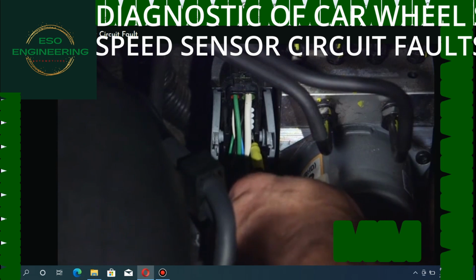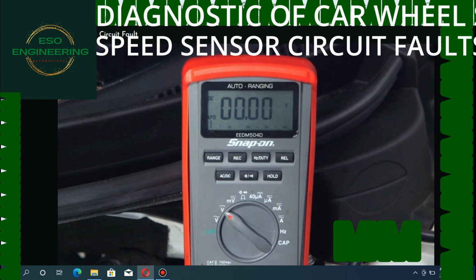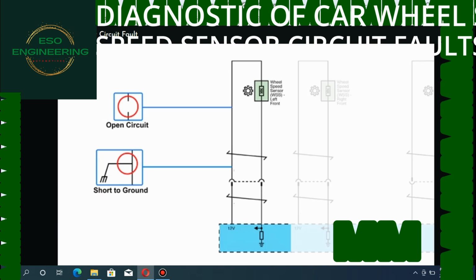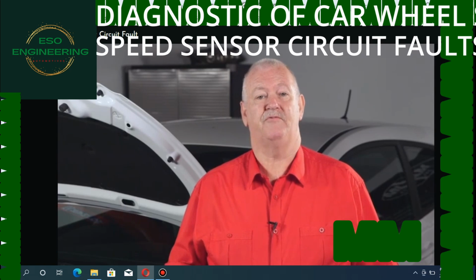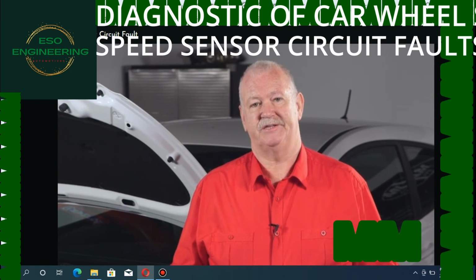Back probe the module to check for the 12-volt reference. If there is no voltage here, then it must be a faulty connector or a faulty module. Check for terminal tension of the connector. If there is no short to ground or no open circuit, then the module will be at fault. If the 12-volt reference circuit is okay, then the signal wire will need to be checked.